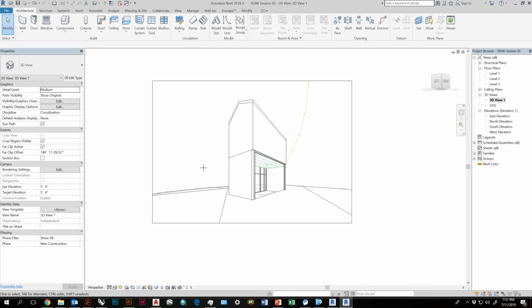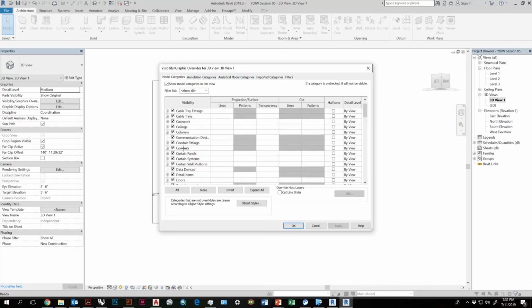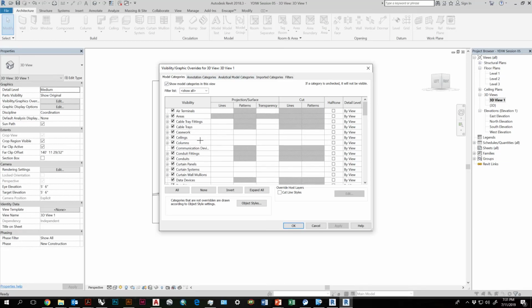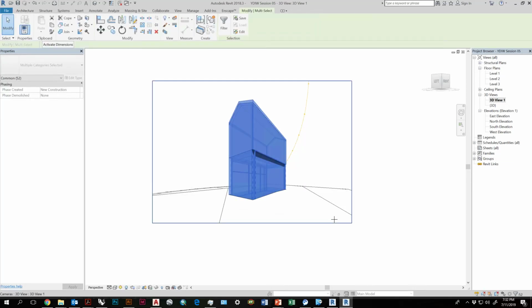Now what I'm going to do is change the visibility and graphics of everything here. So there's no other way to do this, and I've looked, to export just the shadows than this process right here. And this hopefully will show you more things that you can do inside Revit. So I can either go in here and hit VV, which will launch visibility and graphics, go in and change all of these major elements to what I need it to be to export just the shadows, or I can select all of the objects that I want to export straight up. You can hold Control to add to your selection, Shift to subtract from your selection,